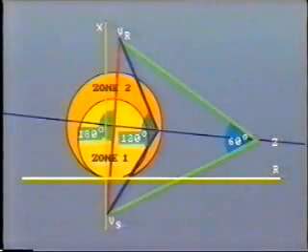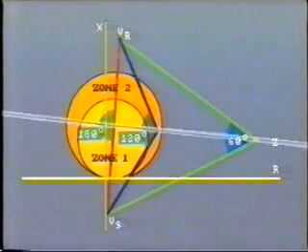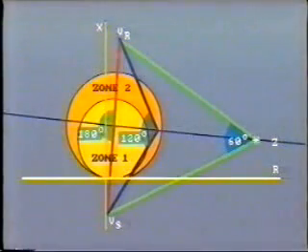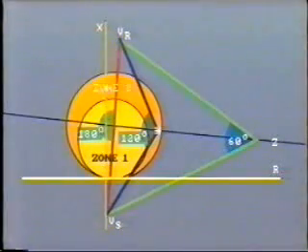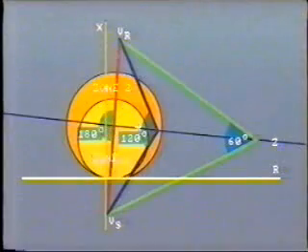This RX diagram shows us how the impedance changes as the phase angle changes between the voltage at each end. For example, where the voltages are 60 degrees apart, the impedance seen by the relay is out here. As the generator rotor advances, the angle increases and the apparent impedance decreases. It will first operate the second zone of the relay, and then after a short time interval will operate the first zone.